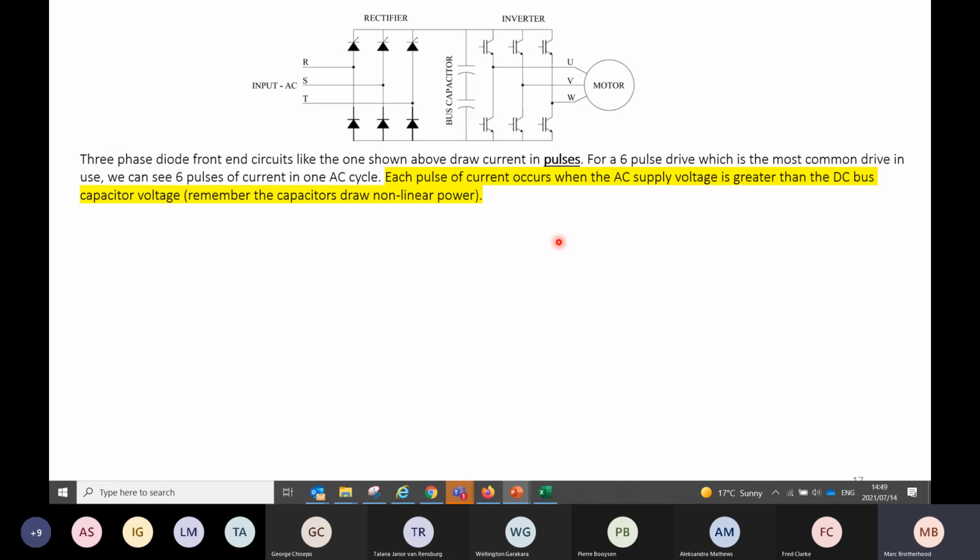So just to refresh what I'm saying, and it gets a little bit important now, these diodes are only going to conduct or pass power through them depending on how much this capacitor is drained. If this capacitor was charged, and these caps will stay charged at about 520 volts, that's why we have big signs on them, do not come near these. They are enough to take bits of metal out of your screwdrivers when you discharge them because the energy they hold is very dangerous. So you must know what you're doing if you want to try and measure this power. But these will stand 520 up to 560 volts.